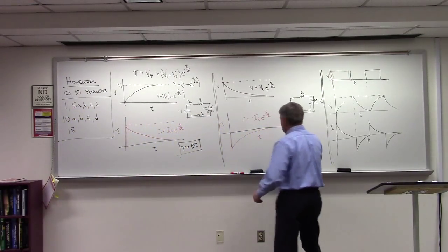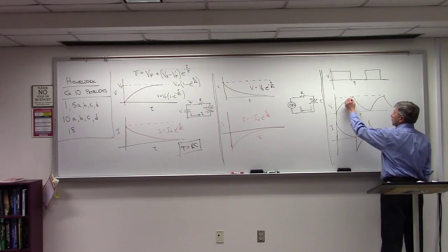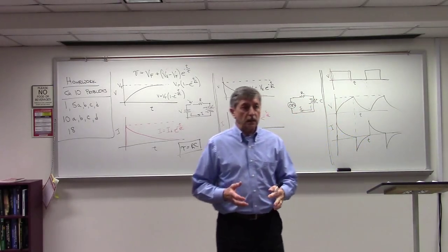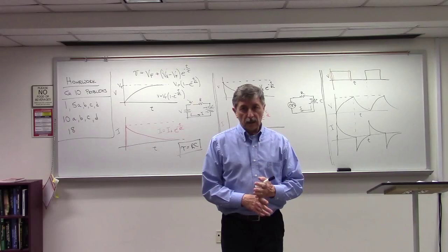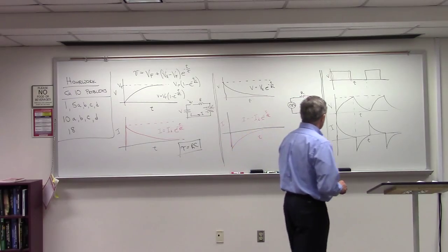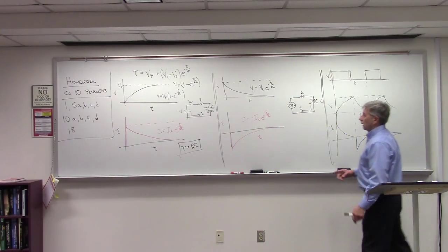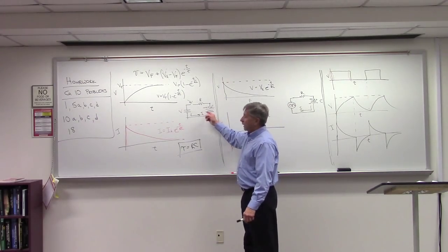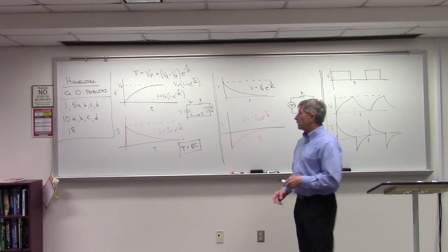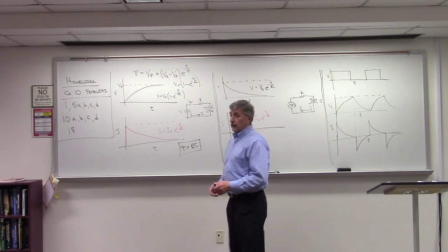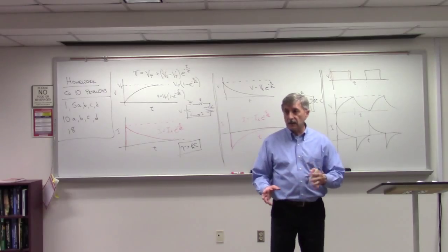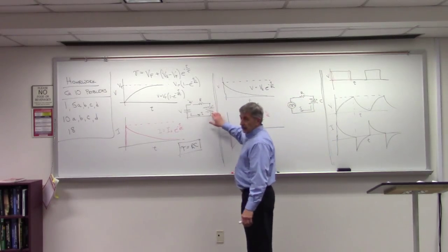And that is an important thing to remember, because what we're going to do next, and this is where we're getting into the latter part of chapter 9, but we're going to be getting into some things in chapter 10 as well. Because when you connect a resistor and a capacitor, not to a battery, but to an alternating sinusoidal source, we're going to find that the voltage waveform and the current waveform, in fact, are out of phase across the capacitor by 90 degrees.